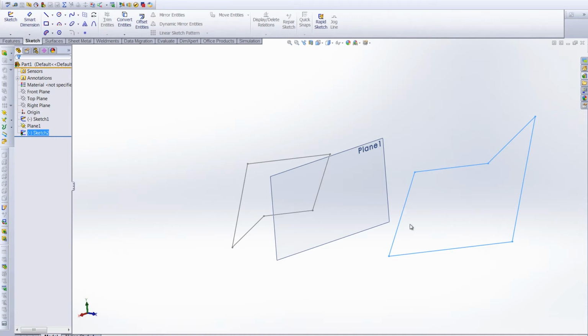So that's the Modify tool in SolidWorks. Like I said, it's highly underutilized for the most part, but it's a great tool if you need to copy a sketch onto a face or a plane, but with any rotation or any translation along either of the axes. I especially like the ability to scale sketches. It makes creating two sketches that have the same profile yet different sizes extremely easy.